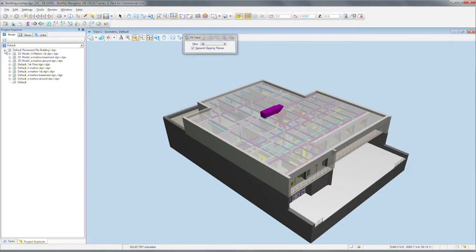You have your plus here, you open that up, and these are all the files that make up this particular iModel. You can see that what we have is the 3D model. Marlowe did that, and so that would have been the architect, Marlowe Associates. Then there's the first floor layout, first floor basement, DGN. The S means it's part of the structural model. The H is heating, ventilating, air conditioning, HVAC, first floor model, and here's all the architectural shell models.